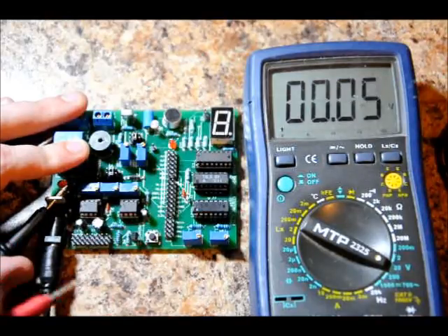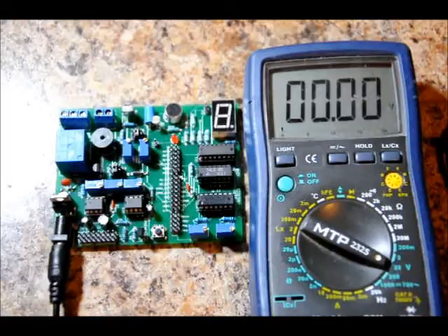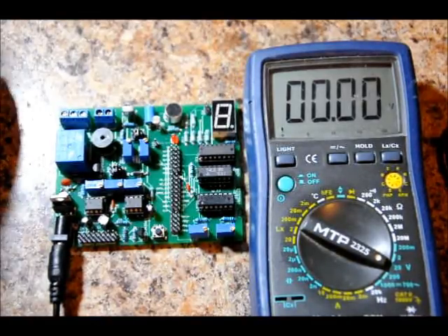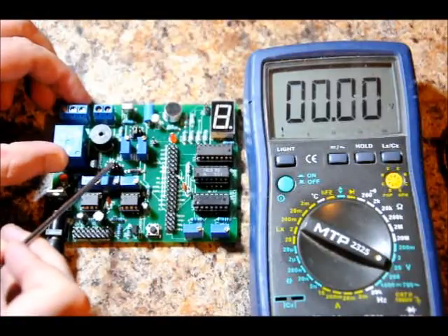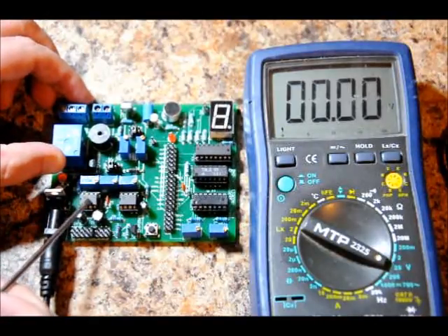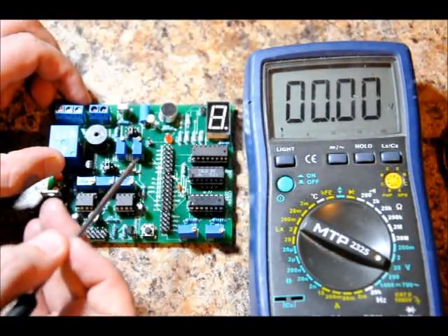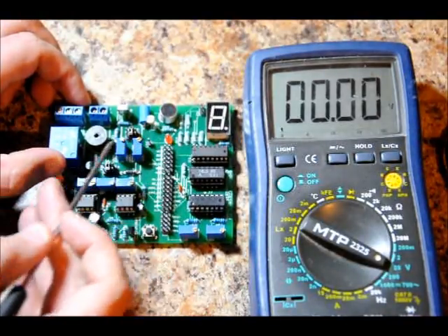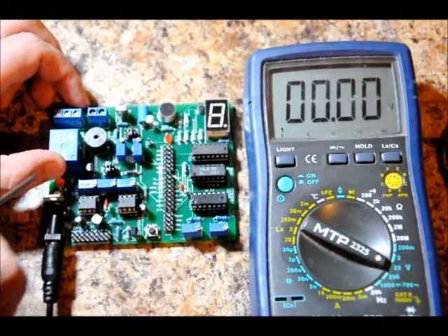Yeah, good enough, 2.51 volts. So we've calibrated our variable resistor. So now what we need to do is there is a 6-pin header up here that determines whether we're using the vibration sensor, the mic, or the LDR. The leftmost pins are labeled mic, the middle pins are labeled LDR, and the rightmost pins are labeled VIB.